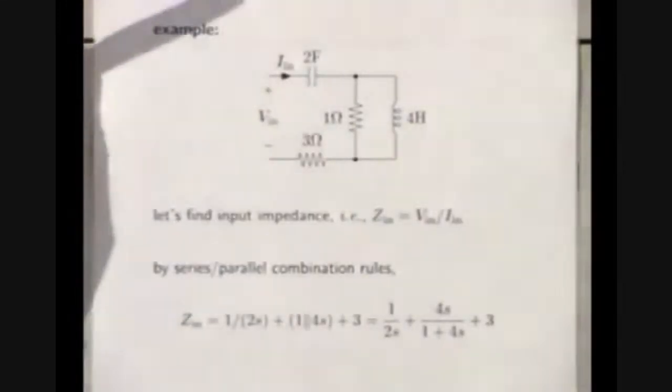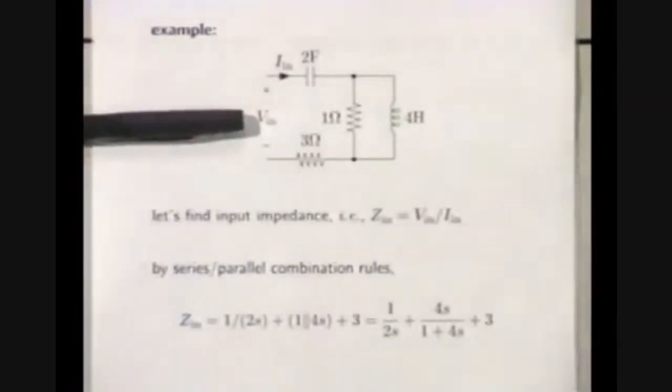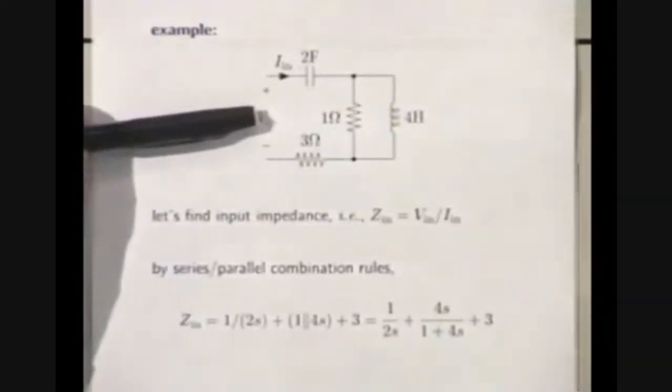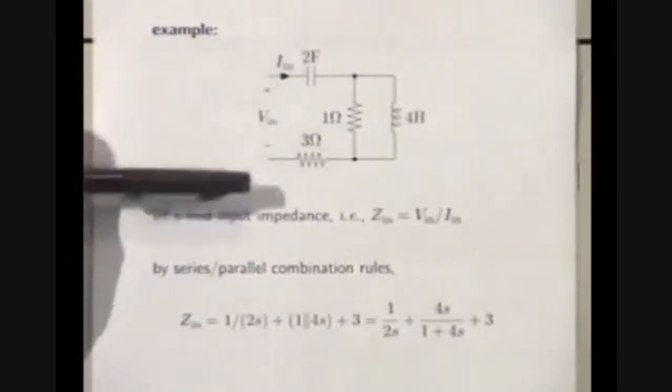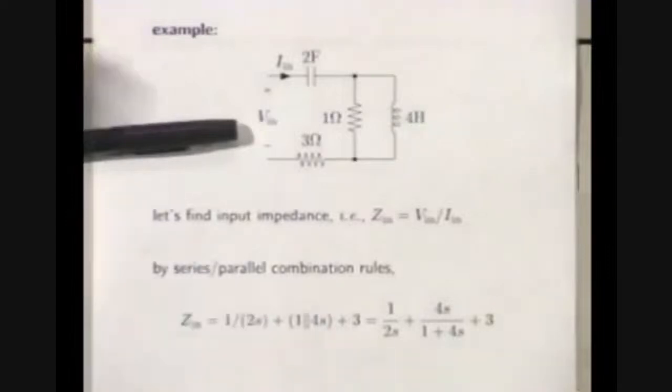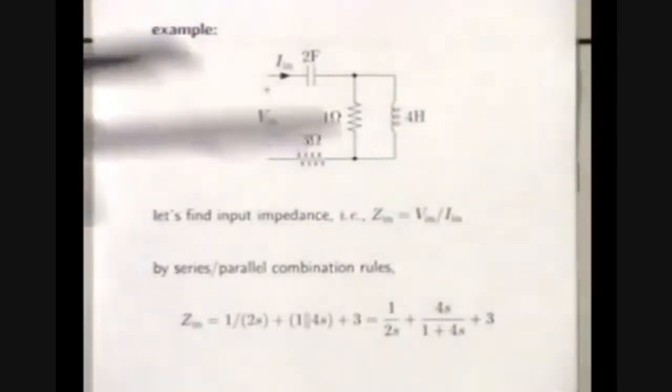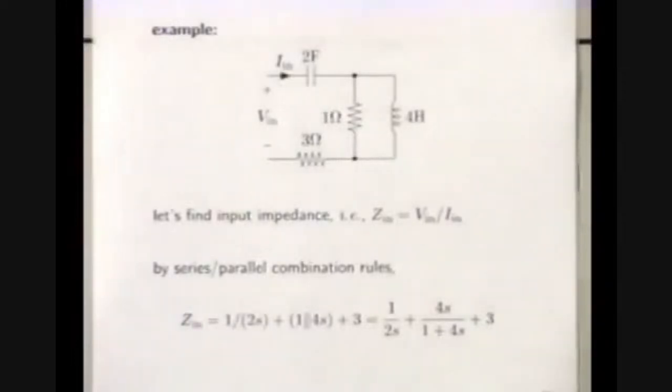Laplace transforms, of course. And also, what I'm beginning to do is what people usually do once you get used to this: we refer to capital V and capital I as the voltage and current. Once you get sophisticated here, you just go back and forth between the Laplace transform and the time domain signal without even mentioning it. So for example, some people would just say, what's the impedance? It's the ratio of the voltage to the current. To be perfectly technical, it's the ratio of the Laplace transform of the voltage to the Laplace transform of the current.